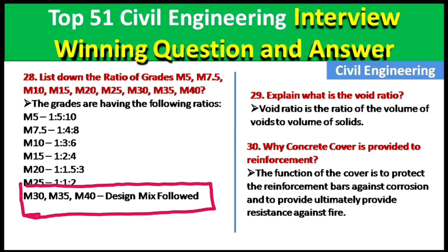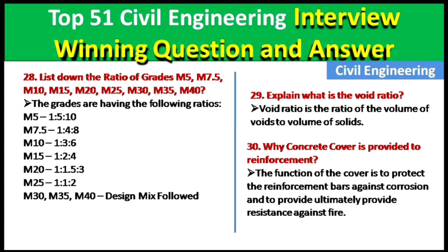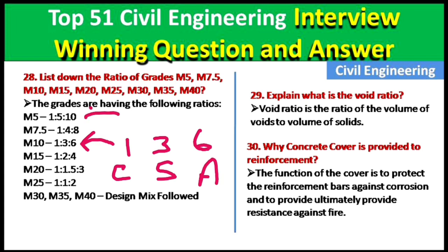I have written an article, you can read. I have put the link in the description. Okay, so you can design any grade of concrete with the help of this article. Okay, so guys, let me tell you what these are. 1 is the cement. Okay, 3 is the sand and 6 is what? Aggregate. In the same way here, 1 is the cement, 5 is the sand and 10 is what? Aggregate.